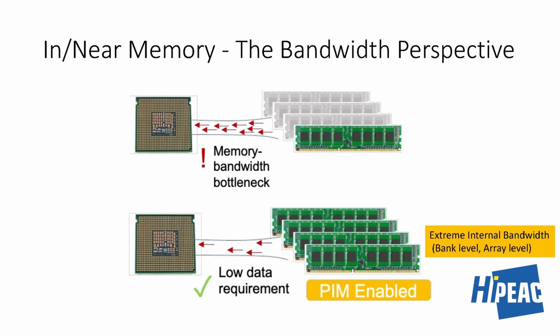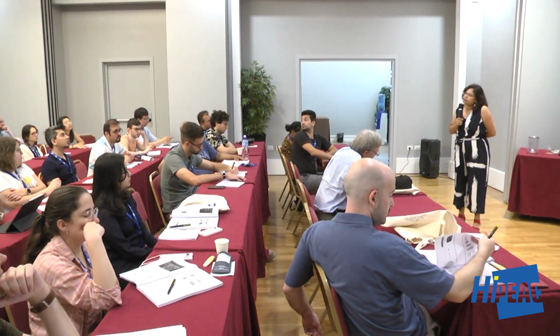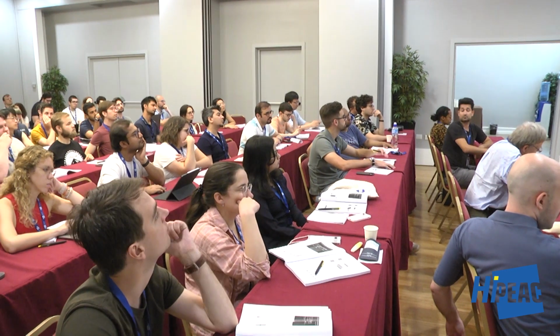Yeah. But in this picture, if you have something like an element-wise operation, do you save anything on memory bandwidth? You still have to read back the data? No, you don't have to read that data. Suppose you have an element-wise operation. That's actually a very good kernel for PIM. So before you would have to read, let's say you had like, I don't know, maybe 100 kilobyte size of the vectors. So before you would have to read 300 kilobytes all to the processor, right?